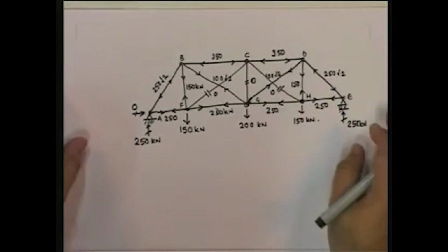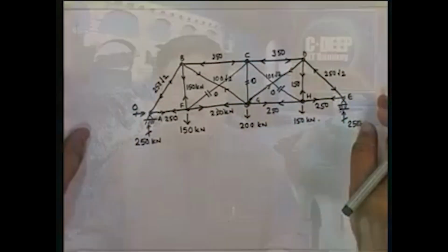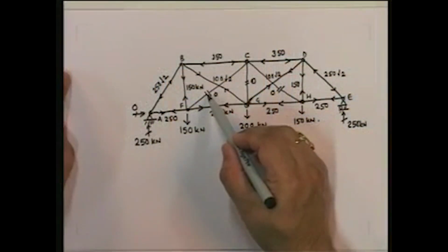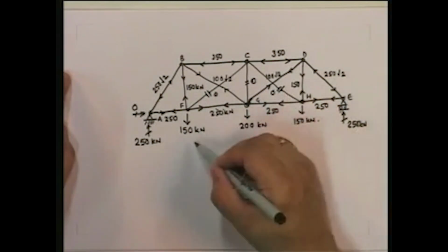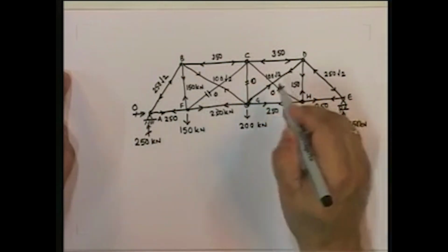However, one other point, that again I am going back, how do we get the additional equation? See, we have 16 equations and 18 unknowns. So we actually need 2 more equations so that we can solve for x1 and x2. How do we do that? That is by actually finding out the displacement of these 2 points relative to each other, given the loading and also given x1 and x2.